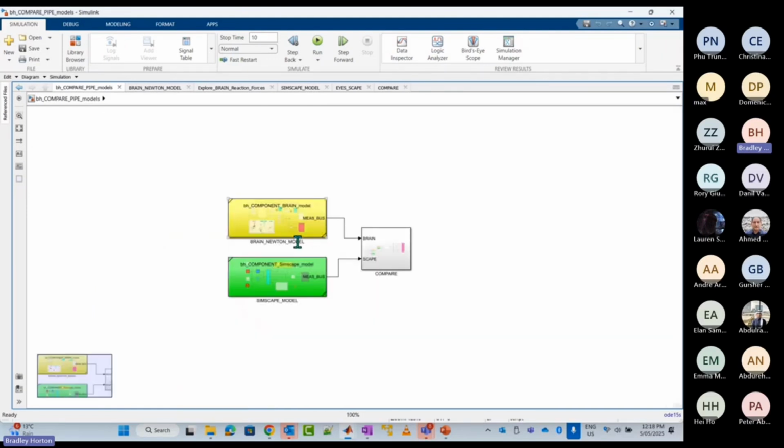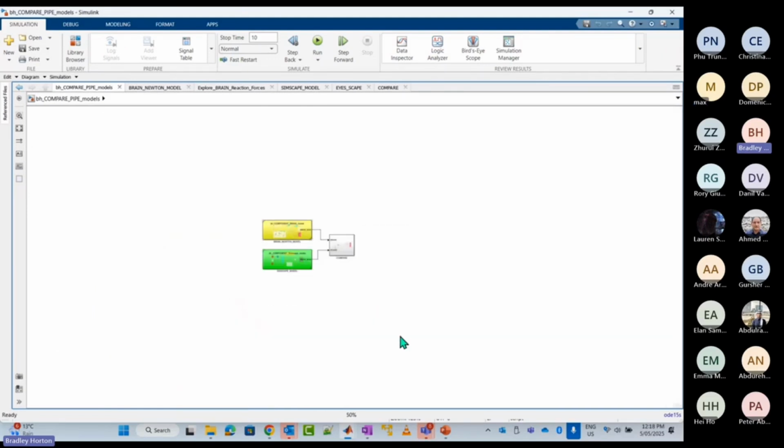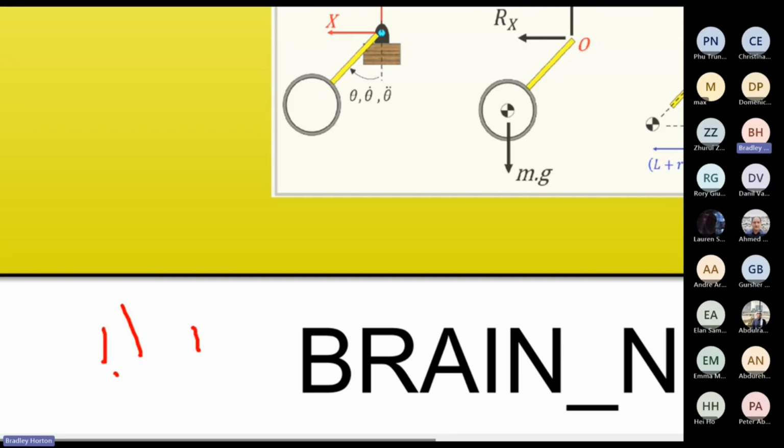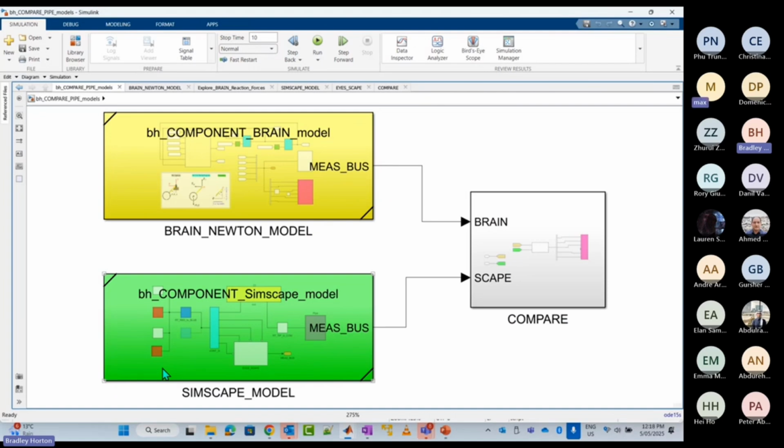If you open the Simulink file and it looked like you were staring at it from 10,000 feet above the ground, or alternatively, if the Simulink file opened and you've got your face pressed against the screen, neither of which are satisfactory, then the way to make the model occupy full screen is just to click anywhere in the white canvas of the Simulink file, and then hit the space bar key on your keyboard, and that should make everything fit nicely into full screen view.